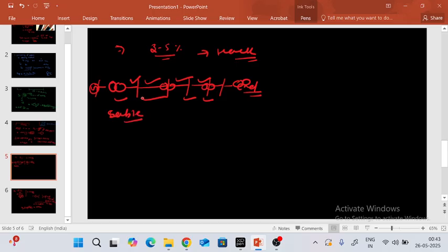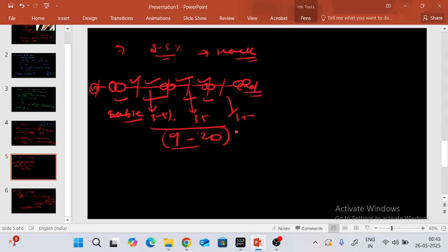If you use 3 to 5% here, 3 to 5% here, and 3 to 5% here, the total goes to around 20%. So this is not acceptable, boss. The meaning of 3 to 5% is end to end, from generation to this point; there should not be 3 to 5% loss at every stage.